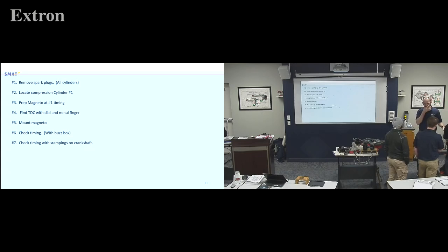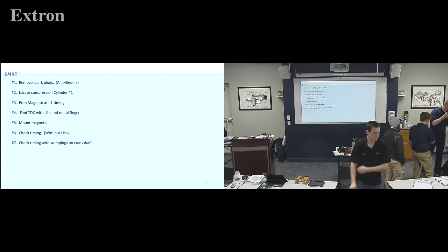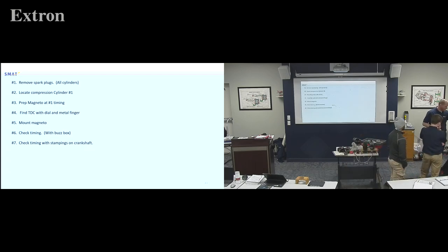So when you divide in half, you're just making sure? Yeah, that's how many degrees of travel we're not letting the piston go up. So you're that many degrees away from top dead center. Correct, yep. So whether we go forwards or backwards, we're that many degrees away. Okay, so sanity check, yep, it's the same. So that's where we would pull that out.